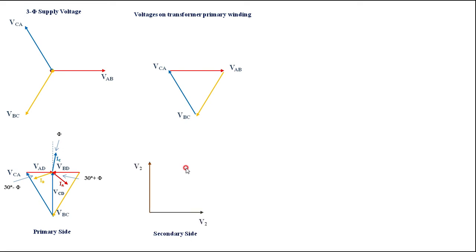if you have got the two voltages, that is V2, the voltage across phase number 1 and phase number 2. Here it is a two phase, therefore the phase displacement between the two phases is 90 degrees. Therefore it is V2 and V2. One is across the main, the other one is the teaser transformer. Then if you are taking a lagging load, the current lags the V2, this is the teaser transformer. Then it is I2M, which is the current of the main transformer which is supplied to the load. It is lagging by an angle of phi.